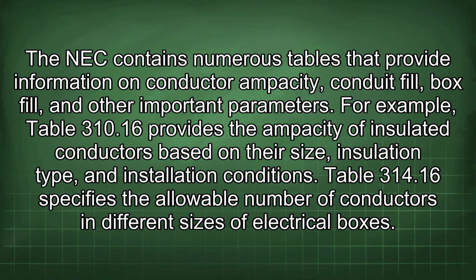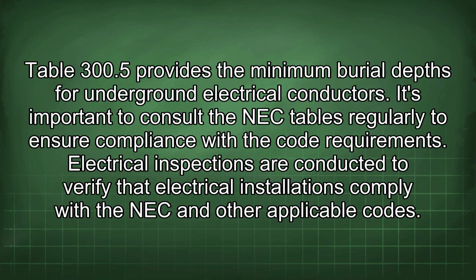Table 314.16 specifies the allowable number of conductors in different sizes of electrical boxes. Table 300.5 provides the minimum burial depths for underground electrical conductors. It's important to consult the NEC tables regularly to ensure compliance with the code requirements.